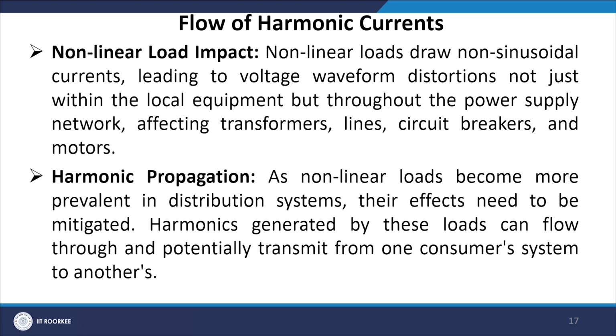Now, when you talk about nonlinear load, it has been told that nonlinear loads are responsible for injecting harmonics. Nonlinear loads draw non-sinusoidal currents, leading to voltage waveform distortion or disturbances, not just within the local equipment, but throughout the power supply network, affecting transformers, lines, circuit breakers, and motors. As nonlinear loads become more prevalent in distribution systems, their effects need to be mitigated.